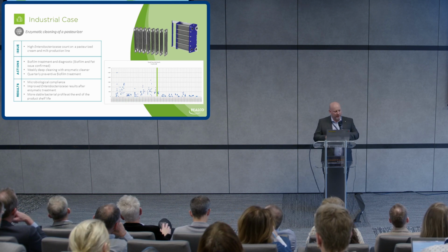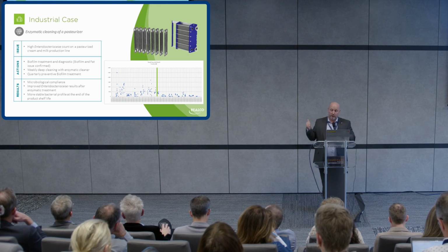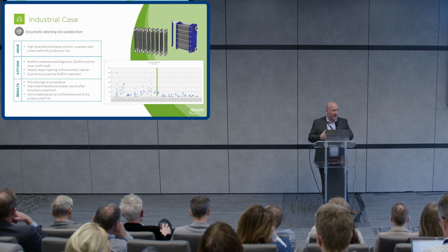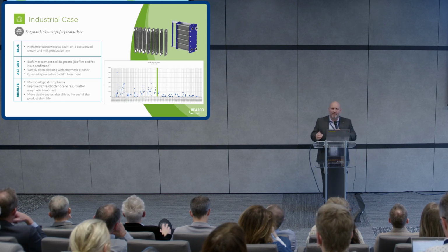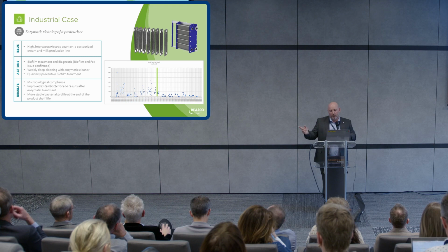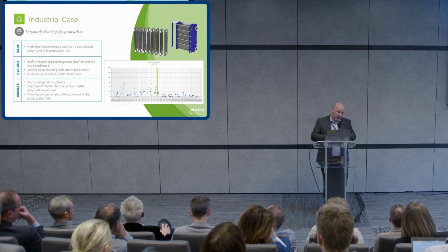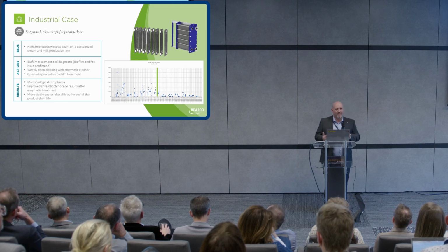So we asked the company to do some weekly intensive cleaning based on enzymes, but here I'm talking about cleaning enzymes, so it's more lipase for fat. And also they implemented quarterly treatment for biofilm prevention. And now it's done, and you can see that the trend is totally different before and after, because the equipment was contaminated with the biofilm and was polluting the product during its process. And this equipment is supposed to reduce the amount of germs, and sometimes that's not the case.